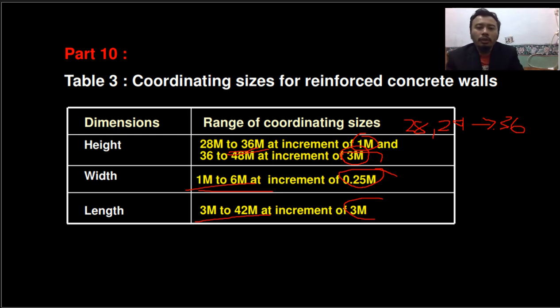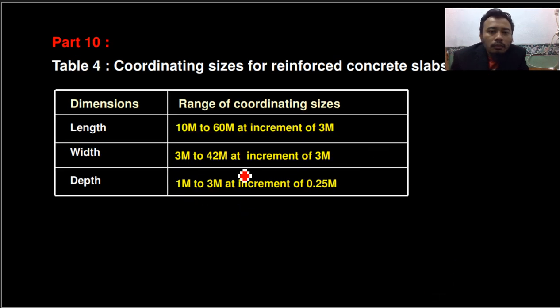So make sure you have this knowledge of the standard, so that when you design prefabricated structural components such as columns, walls, and beams, they fit within this implementation, so that they can be adopted in other modular coordination. When all the designers of the building use modular coordination, it will be well suited.